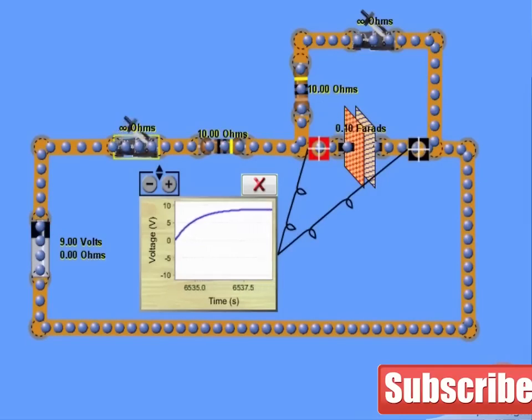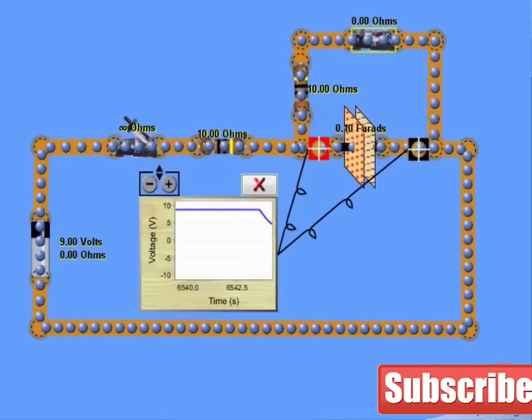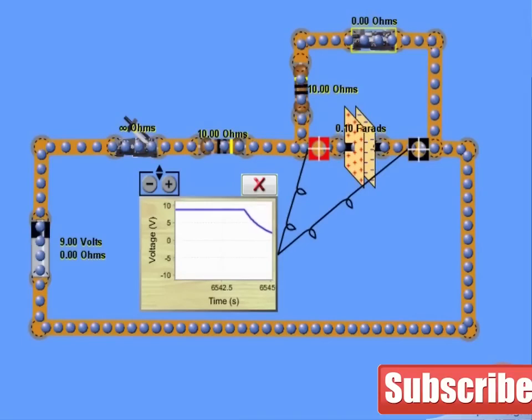If we look at the discharge curve, since our values are the same, we should see the same time. Coming down from 9 to 4 volts is going to be our RC time constant. Let's try that. 1,000, 2,000, 3,000. So this circuit has an RC time constant of approximately 3 seconds.